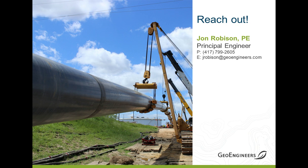That pumps fluid, just plain water or water mixed with something, to the microtunneling boring machine where it is introduced into the ground, mixes with cuttings, and then those cuttings are pumped back to the ground surface to a fluid recycling plant where they're run through sieves, the cuttings are taken off, and the fluid is recycled for reuse.